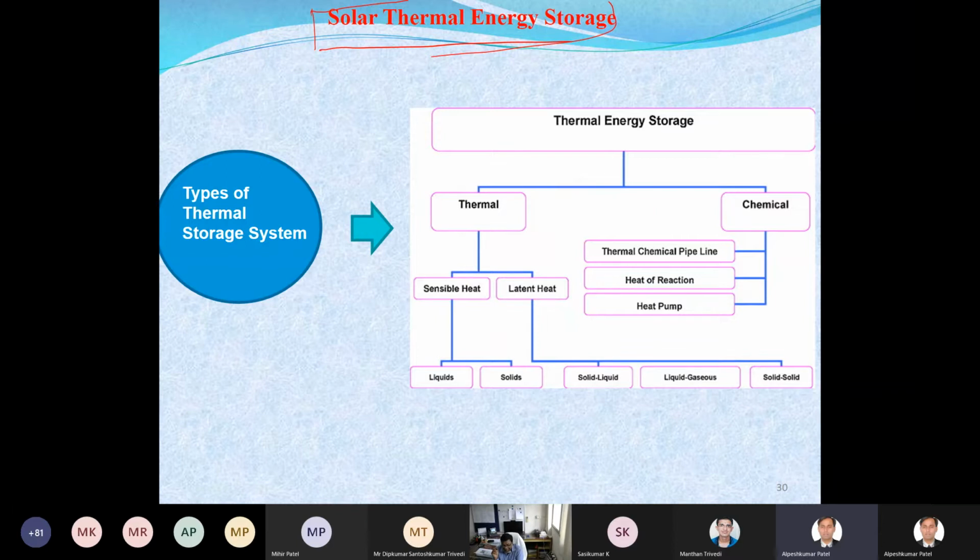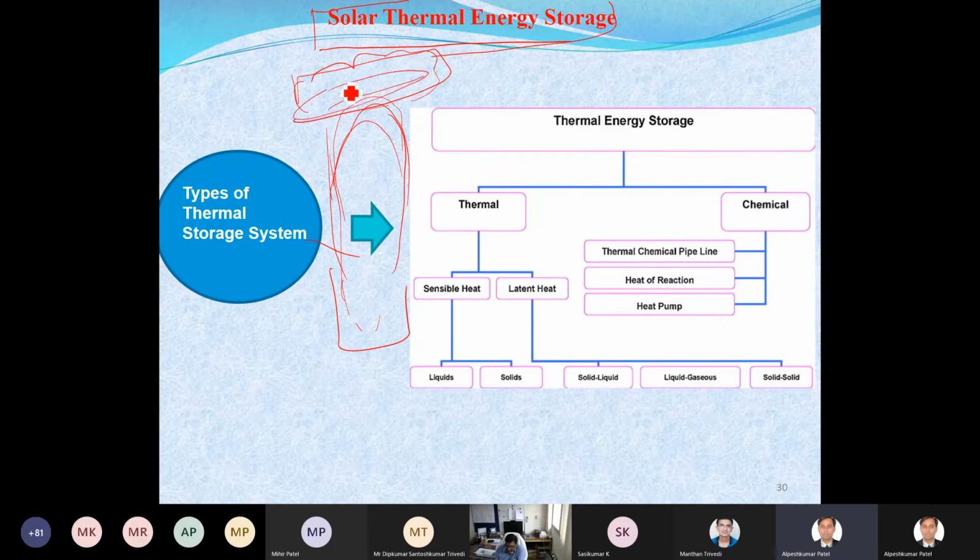all the hot water systems have storage, because you can see that tank over there is a storage. This storage is full of hot water, and it is insulated just like a geyser in your house. In the daytime sunshine will be there, and that hot water is circulated by the thermosyphon process. There is no extra pump. So through thermosyphon it will heat up and be stored, and then when you want to use this hot water, you can use it. So this is storage. That means with this low temperature requirement, you need storage.